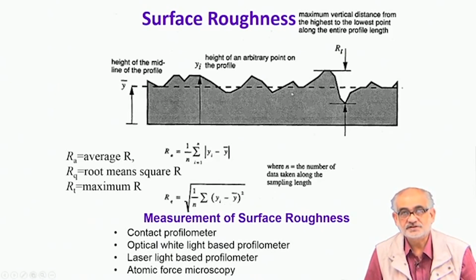The size and geometry of those grits on the grinding wheel or the abrasive particles would leave such asperities on the surface. But if this amplitude is submicron, less than a micrometer, then you don't distinguish them by your naked eye. So you essentially tend to see a very flat and shining surface.